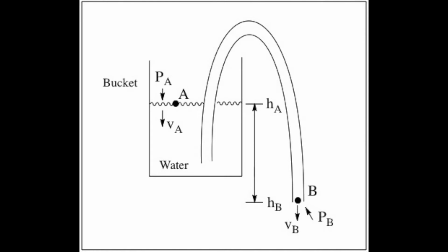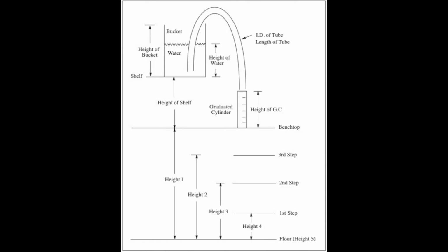To model the flow rate of your siphon, apply Bernoulli's equation to the system. Outline a clear explanation of any assumptions made in the application of Bernoulli's, and clearly identify the initial and final points of fluid flow presumed. Note that while you're performing 5 different trials of 5 different heights, how you choose to measure these heights to aid in final calculations is purely up to you.